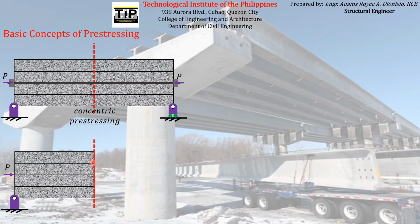So again, if we have cut a concrete beam, we know for a fact that there is an internal force that will come out, and that internal force should balance this external force acting on the concrete beam. So it must act along the same line of action as this compressive force, same magnitude, but opposite in direction. So the internal force that will come out when we separate this segment from this segment will be this. I just moved the force from this part to this part, just to have an open space here.